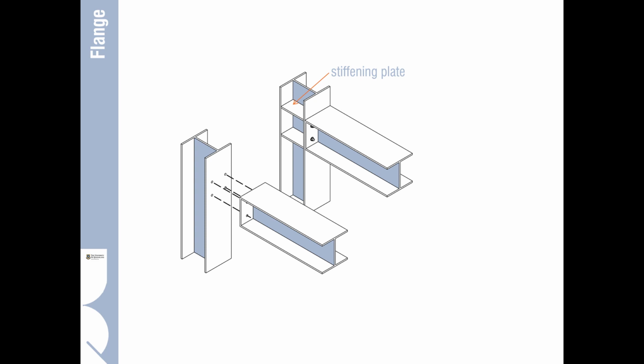The other typical steel connection is where we get beams connecting to columns. Now often the flange widths of universal beams are not the same width as the flanges of universal columns. So we do have to make sure that we understand the relative dimension between them.